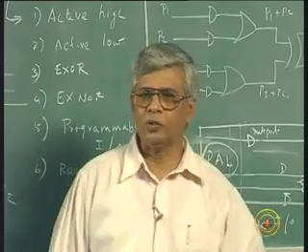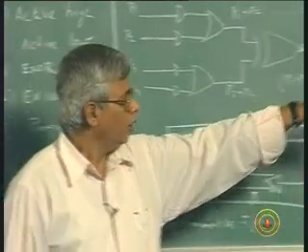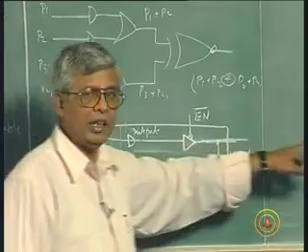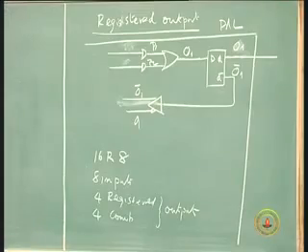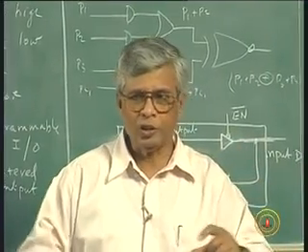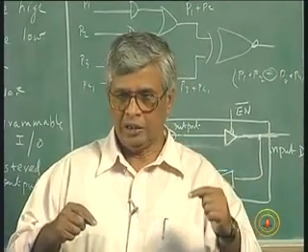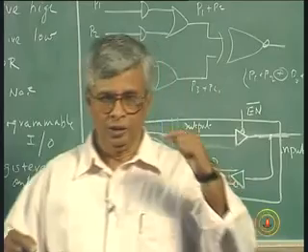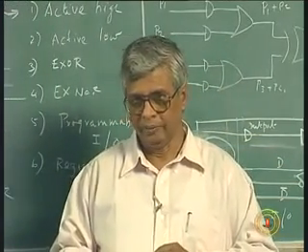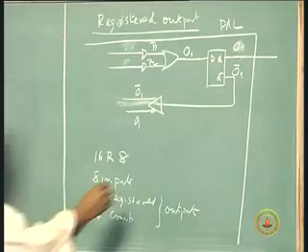And then all other features. But then when you have this programmable feature, you need extra inputs. You need a clock signal, you need an enable signal. All of them also have to be given. So when I decide the number of pins required, number of inputs, number of outputs, ground and power supply, is a clock required, is an enable required, all those things also are accommodated. So clock comes from, so this has to be clock, remember.